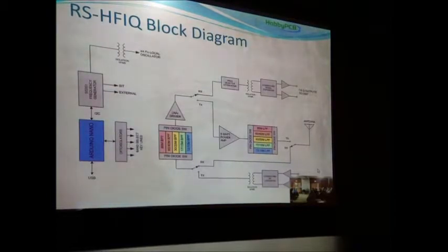And then it goes into what I call a frequency selective attenuator, which has more loss at the low frequencies and less loss at higher frequencies. So the overall front end of this radio has about 0 dB gain at 80 meters and about 12 dB gain at 10 meters. So when you're operating in an environment with lots of very large signals, it doesn't tend to overload the mixer. But when you're operating at the other end, at the higher frequencies, where weak signals and noise figure are more important, it has more gain. And it's worked out pretty well.